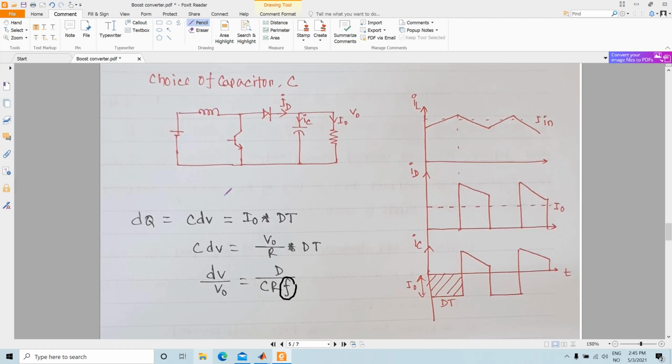But there is a limit to how high you can go, because the higher the switching frequency, the more you increase the switching losses in this transistor. So there is a limit beyond which you cannot increase your F. You normally try to increase your F because increasing the frequency will reduce the size of your circuit, but there is a limit after which, if you increase your F, your losses will increase more and more. Above that you are not interested in increasing your F anymore.